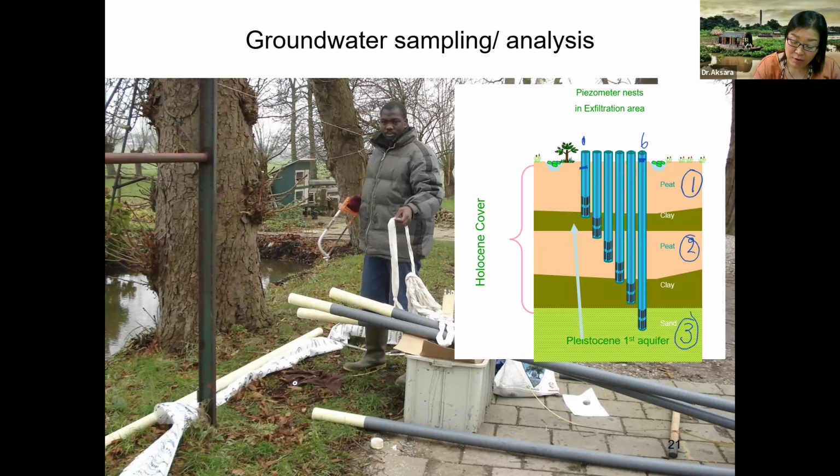And for wells 2, 3, and 4, they're from the same depth, so they probably have pretty consistent piezometric head in those 3 wells. Okay, I'm just going to change my drawing a little bit. And for 5 and 6, pretty much the same. Sometimes you get a really high pressure in the confined aquifer, and it has higher equipotential head compared to the unconfined aquifer. Okay, done.